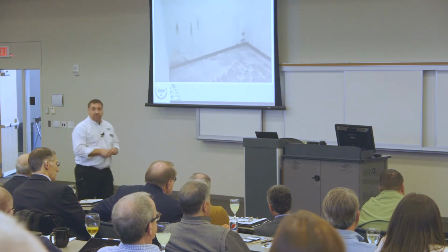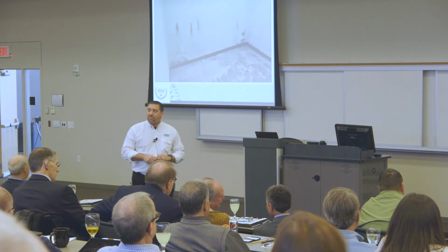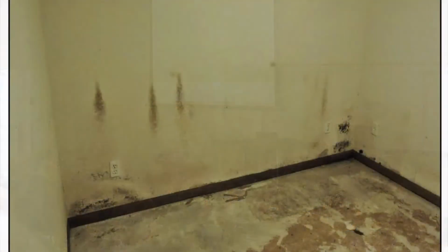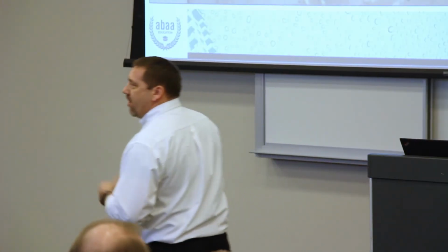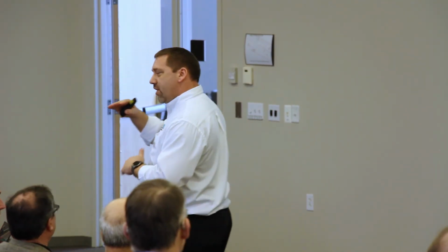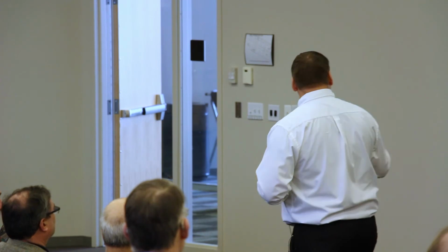Basements, we talked about basements and the moisture down there and making sure they're built properly and everything else. They put 6 mil poly from about 4 feet down. How do I know? I ripped it apart. That's again why my lungs are going to be so cool when my autopsy is done. Right? Only the bottom 4 feet, for whatever reason. That's all they put the poly on. And that's where we had all this major issue.